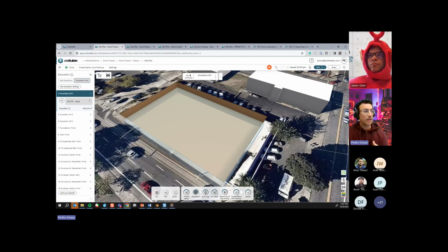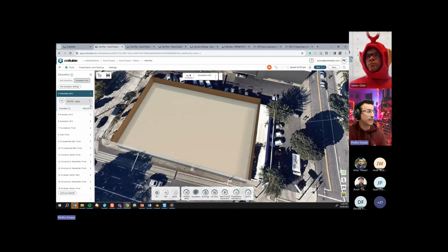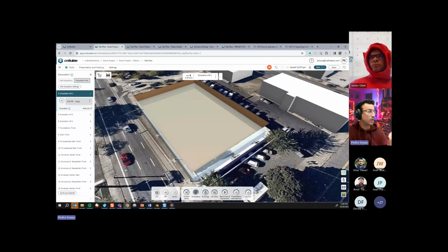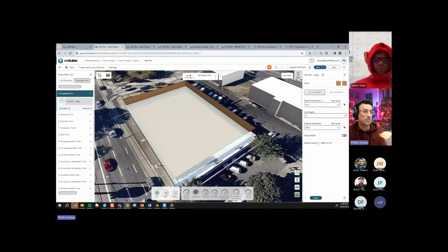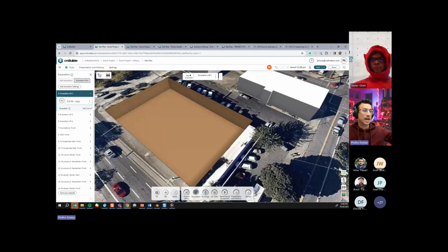However, as a quick workaround, instead of creating a duplicate and moving it down, you can either create a new cut, or you can create a cut that is slightly bigger or slightly smaller than the previous one. You can create an offset over here, for example, and bring this cut to be slightly bigger than the previous one. So that second cut is not going to have the same face as the previous one. This is more for when you are recreating the same cut several times. If you notice that your performance starts to decrease, it's because of that. So you can use this workaround.